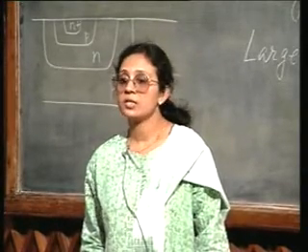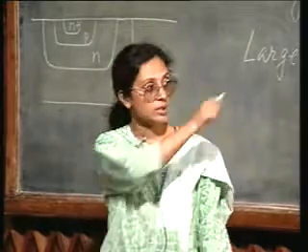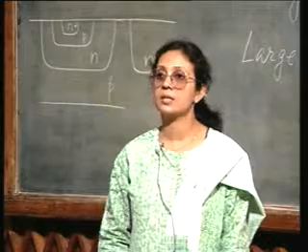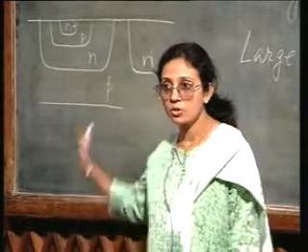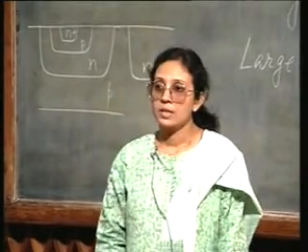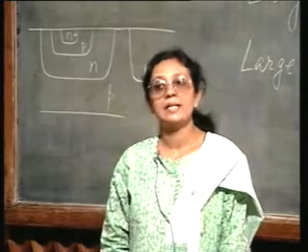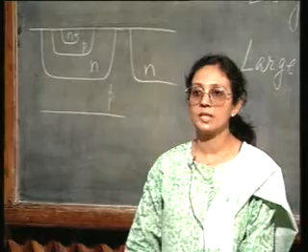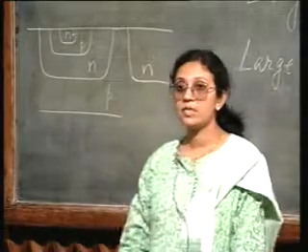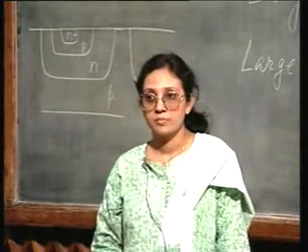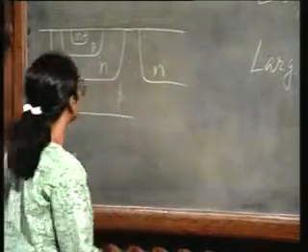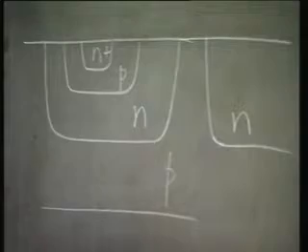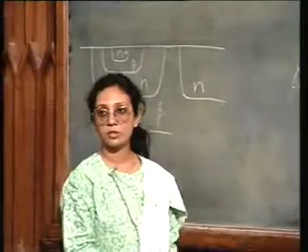And because this p isolation diffusion in this particular case had to be very deep and therefore resulted in a considerable lateral spread, you could save some area. So, some improvement in packing density was achieved if you have these 3 diffusions, because you no longer have to have a p isolation diffusion, which will result in considerable lateral spread.